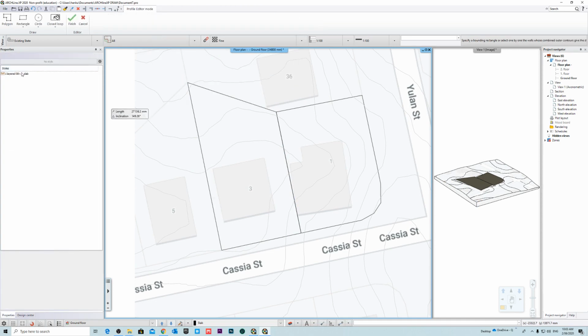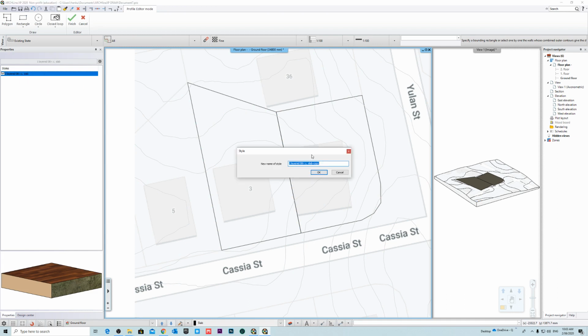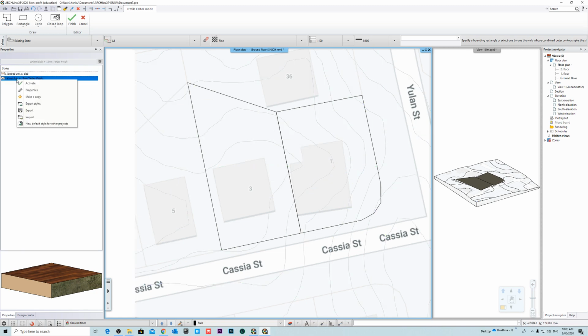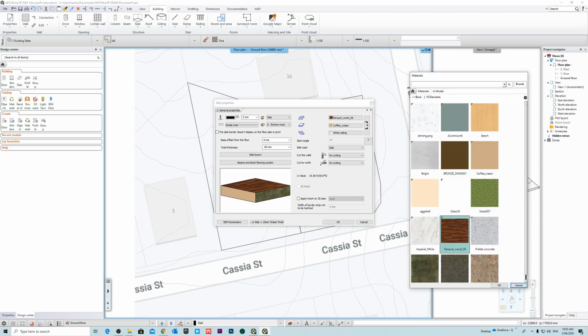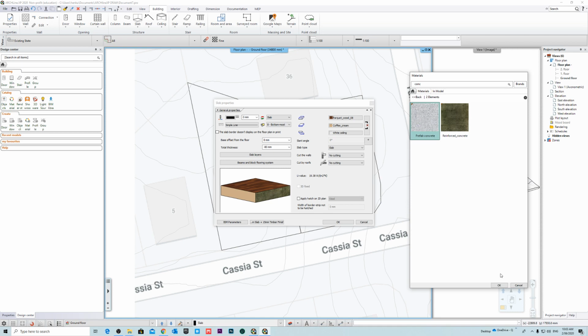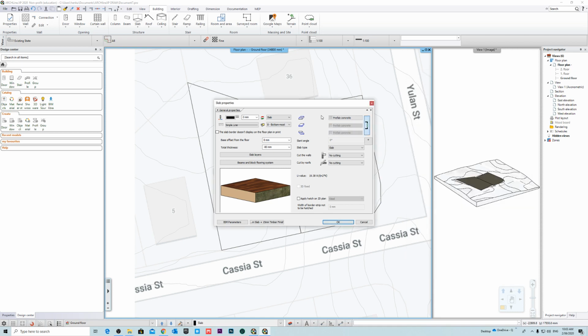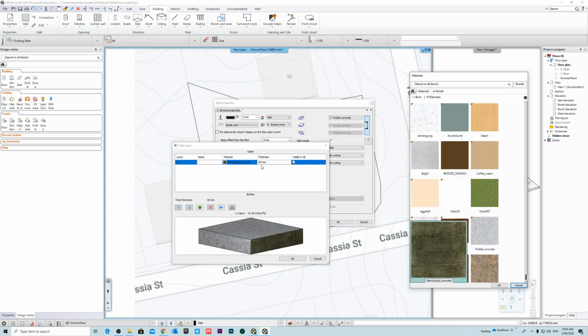Okay, so I'm just going to go make copy, and I'm just going to make it 100mm slab plus, say, 15mm finish plus 15mm timber finish. Okay, and I'll just go OK. And let's just make some quick modifications to this. Okay, prefab concrete, and we'll just go like that.